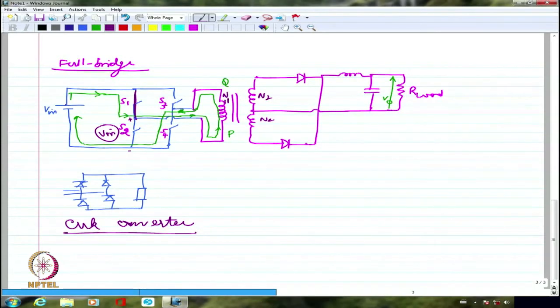So this is the last converter that we are going to discuss. This is not an isolated converter. Many of these converters also can be made isolated, because wherever inductances are there, they can incorporate a transformer. It's not that they cannot, right? Wherever inductances are there, you can think of a leakage reactance of the transformer working as an inductance. That's not a big deal. So many times a non-isolated converter can be made into an isolated converter by making the inductance represented by a transformer. So you can make it isolated if it is required to do so, right?